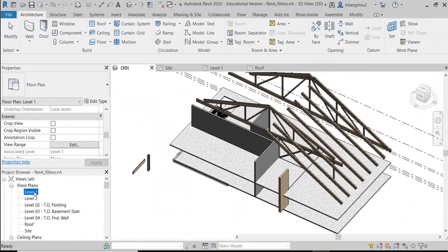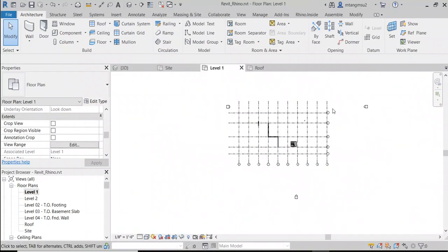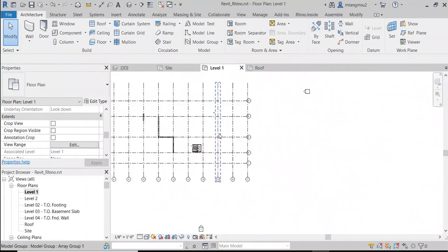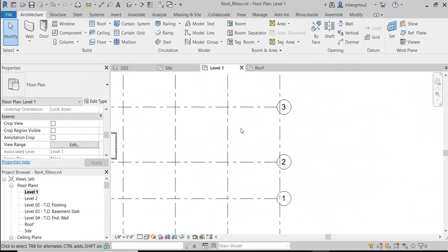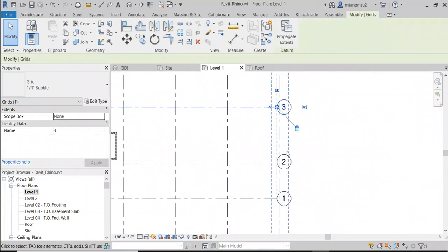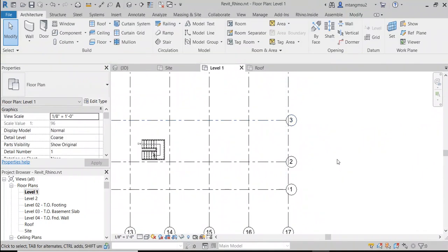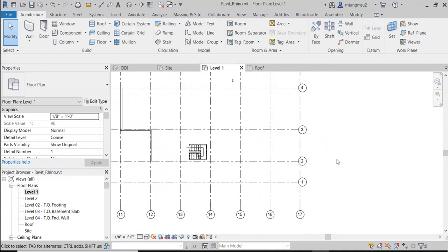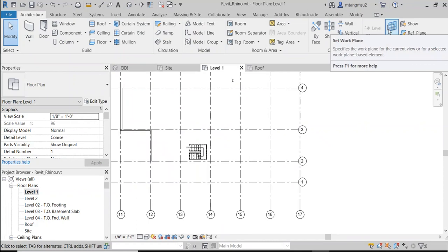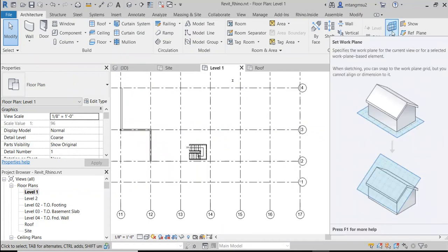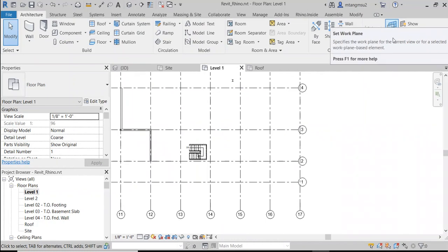So in general, when you work on a Revit project, this is my way. I will create a grid system. The grid system is really useful, especially if your site is not true north or true south, right? Maybe it's diagonal, it's tilted in certain orientations. So in that case, in the future, when you set, for example, a reference plane, this will be some working plane. You can create lines, you can make objects, right? So this is called working plane.